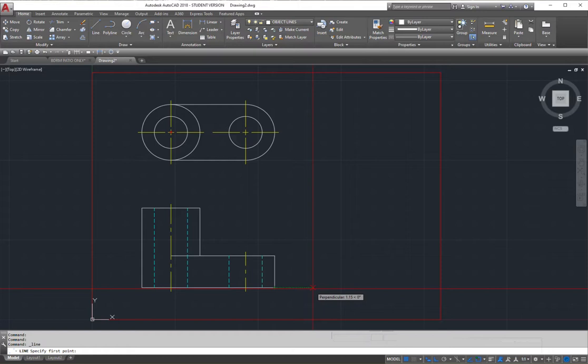It just tells me. So I'm telling my computer right now that from this reference point, I want to start something 1.5 units away. So if I type 1.5 enter, it actually goes and starts there. And I'm going to deactivate my F8 so that I can just go in that direction. Now I will have to have my F8 on if I want to go straight right here or across. But if I go, for example, and I want to create a line that is the same length as this one, because they're supposed to be the same thing right here, right?